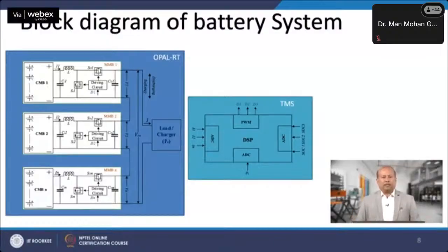Let us discuss the working principle of the battery system. The system consists of 3 modules and a boost buck converter, each to step up or step down the battery voltages as per the requirement. Such a mechanism is called energy sharing because each module can be controlled individually, which resembles the sharing of the power demand accordingly.